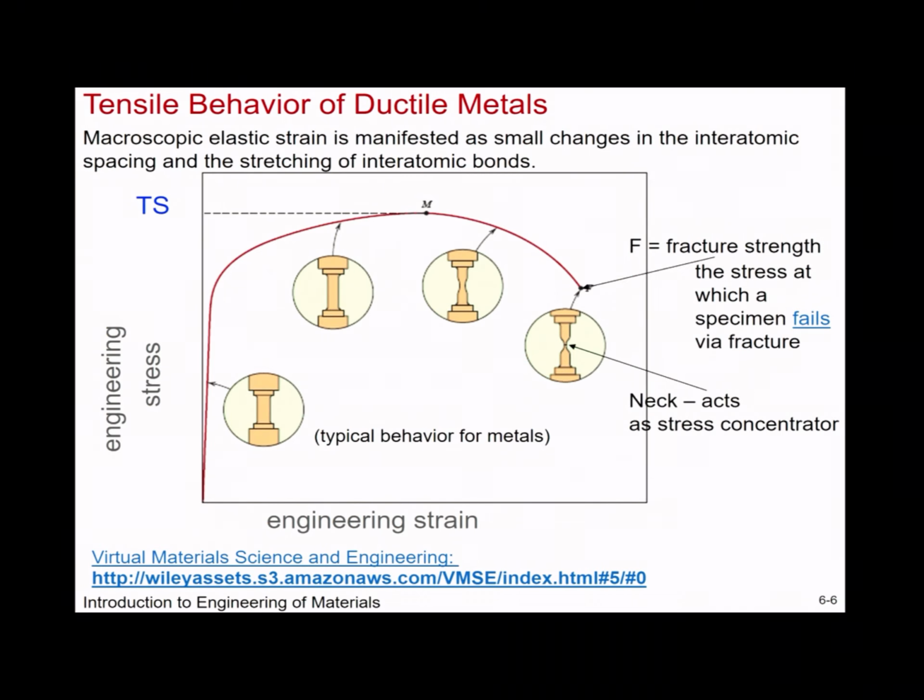Okay. So what's happening when we pull this in tension? We'll go into this in a little bit more detail if we get to the video in time. But basically, you have this linear region. You have your sample that looks like this sort of dog bone type sample where you are inducing the breakage somewhere in that section, in the gauge length. You'll experience a linear regime, and then your stress will actually decrease because this is engineering stress, and you're normalizing by the initial cross-sectional area.